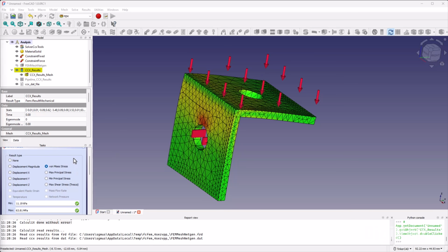Von Mises assumes a ductile material. That means the material, in this case our plastic, can bend or stretch before fracturing. Most metals and some plastics are considered ductile. PLA and PETG are generally considered somewhat ductile. They might have some inaccuracies, but that's okay. Things like acrylic are very brittle, so the von Mises stress calculations would not work here.